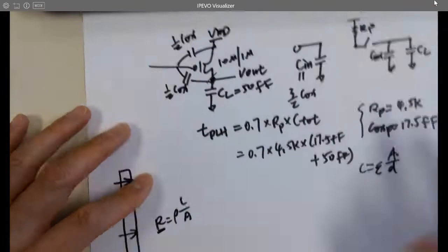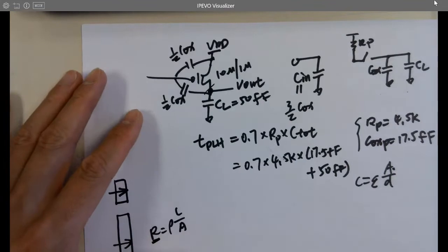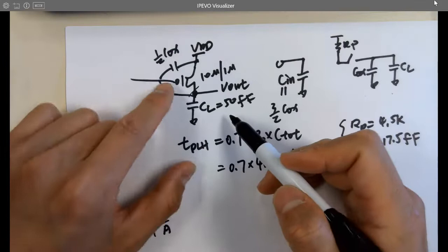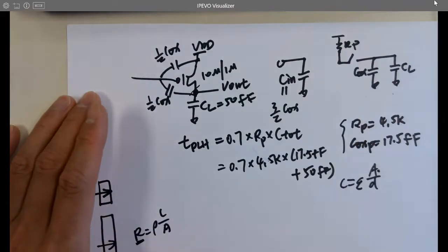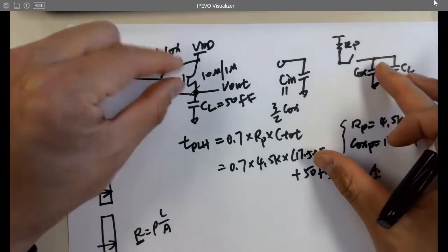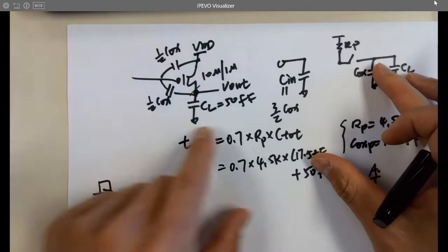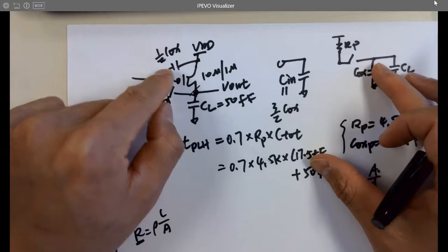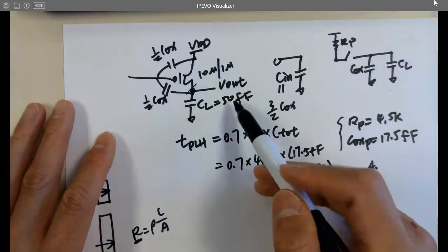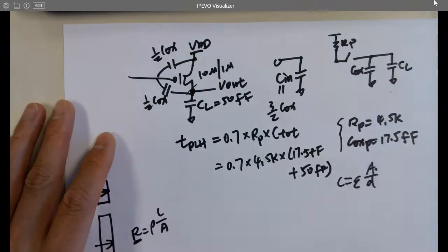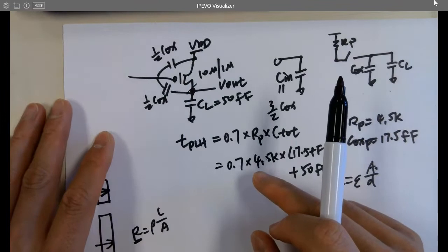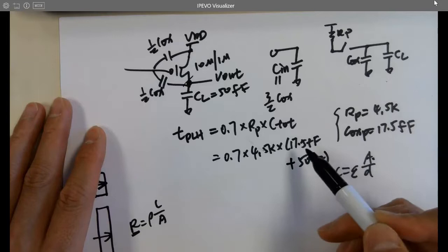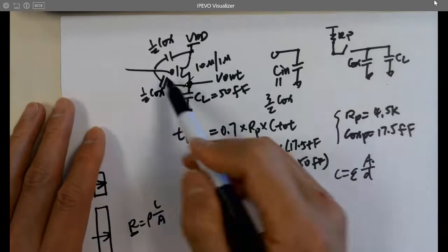Here is calculation at middle school level. Sometimes the load capacitance can be pretty high, especially when we are using 180 or even smaller, like 40 nanometer technologies. The capacitance can be even smaller because the footprint of the transistor is smaller. So the capacitive load can be relatively higher compared to the channel capacitance, and then you can ignore the channel capacitance and only consider the load capacitance. For example, if this becomes 5,000 femtofarads or 5 picofarads, then adding 17.5 femtofarads, you can ignore it. It's not contributing too much delay. Directly use 5,000, right? Don't bother calculating all the small capacitance.